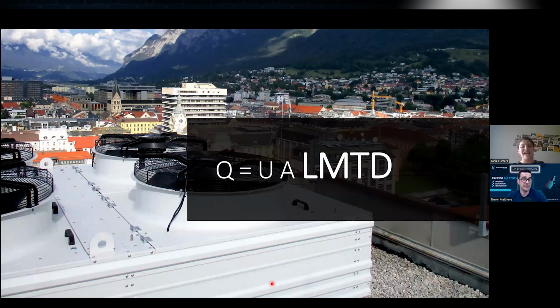So it's never free. We can get more capacity, but someone has to pay the price. Yep, that's totally fair. And on the high side, we have the condensers, gas coolers or fluid coolers. If we have a refrigerant that doesn't have a phase change, the difference will be between the refrigerant and the ambient temperature.